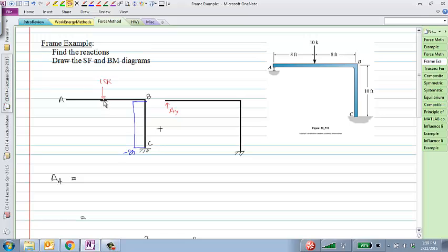Right, so if I take a cut somewhere here, then the internal moment at that point would just be 10 times that distance. So let me label that. I'm going to call that x1, and it would just increase linearly with that, and I'm drawing negative because the displaced shape of this would look something like that, right? Maybe I'll draw that too.